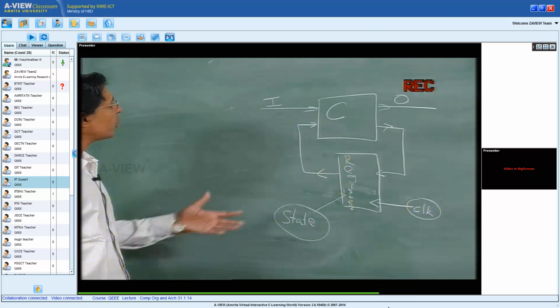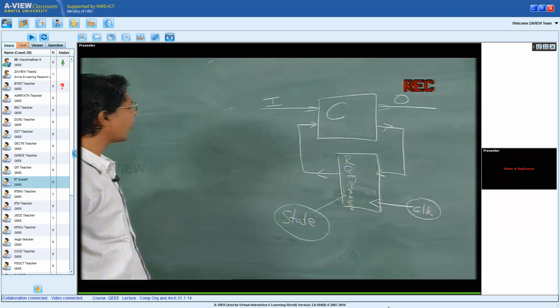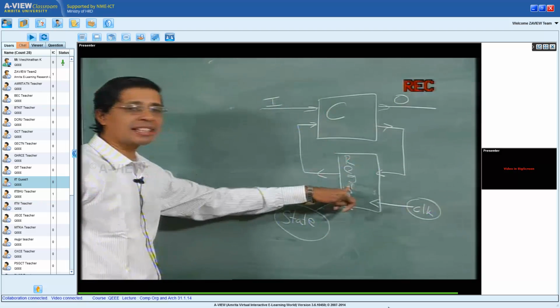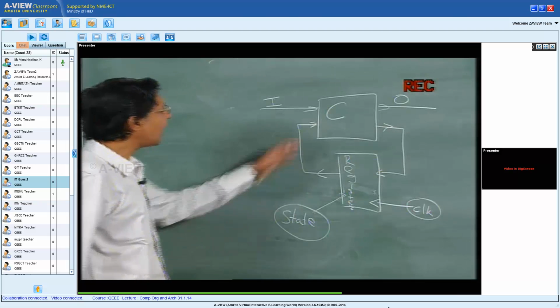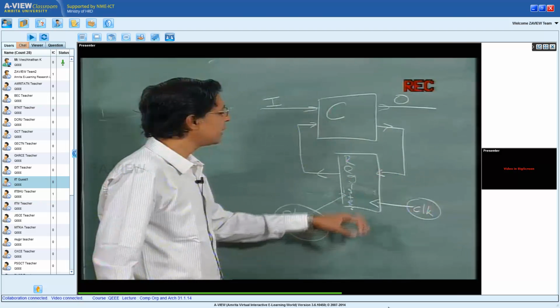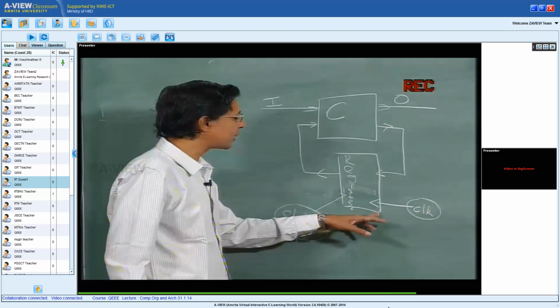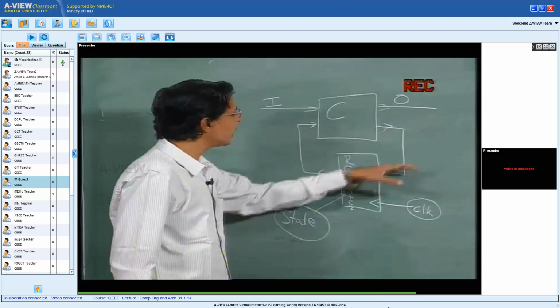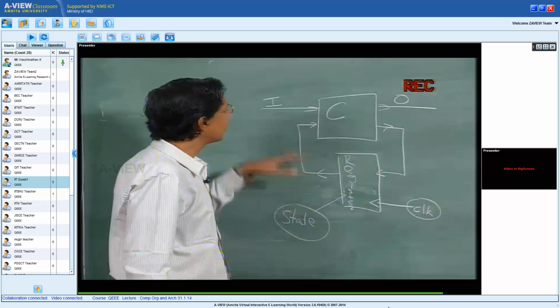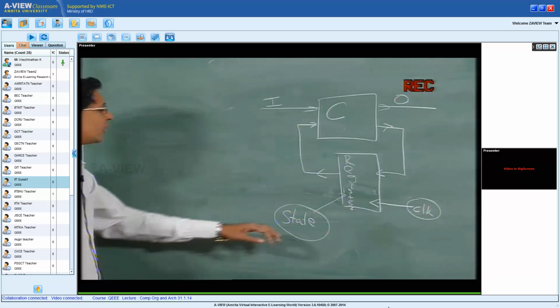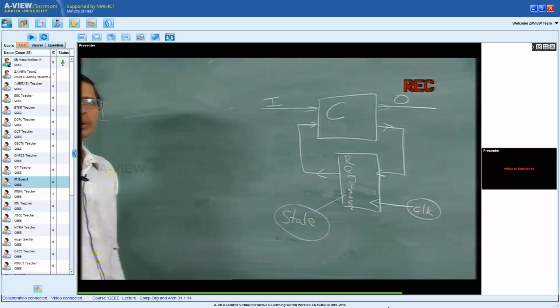The output of a sequential circuit is a function of the current inputs and the state of the circuit, and the state is updated at every clock pulse. When the new clock pulse comes, the current state is stored and given as input for the next clock cycle. So this is how a sequential circuit works.